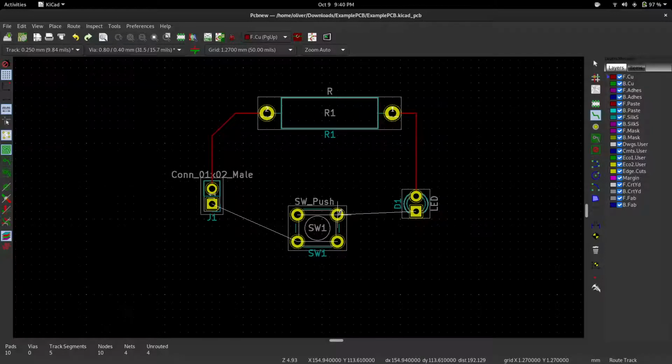I'm going to draw a trace from here to here to here. Now, because this is just a little board that powers an LED on and off, there's absolutely no reason that the shape of the trace or the length of the traces matter. If you're making some board with radio frequency stuff, that's when it starts to matter, but we don't care here.